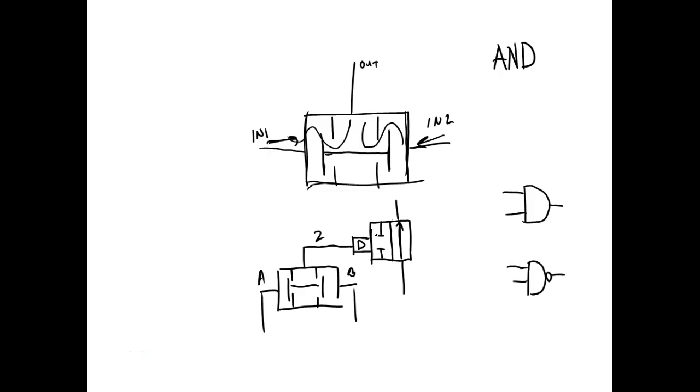And by the way, this is a NOT right here. So it's real simple. We've run into a NOT before. So a NOT is nothing but a normally open valve. That's all it is. So that's a NOT. You understand that? If I don't do anything to it, the air flows. As soon as I put pressure on that side, the air cuts off. So that's a NOT.